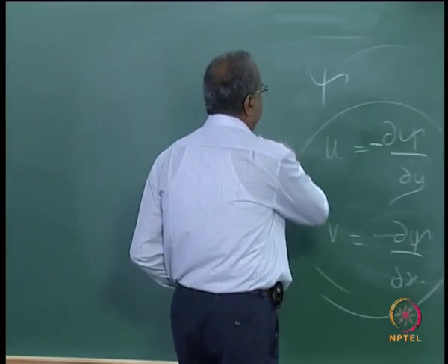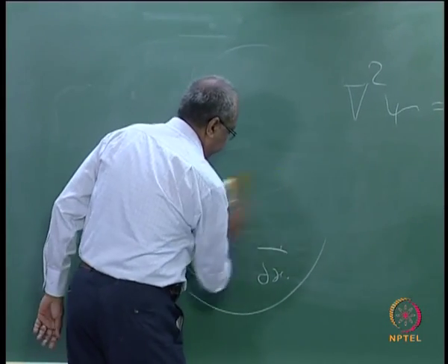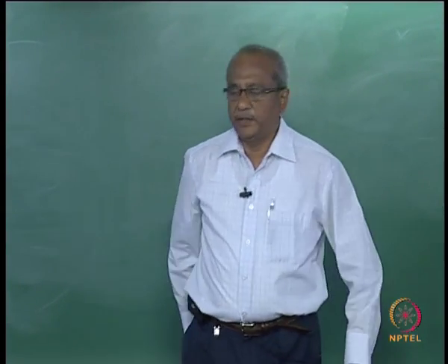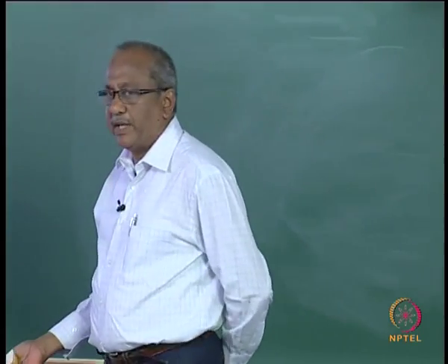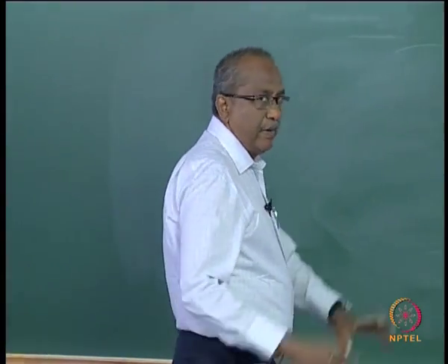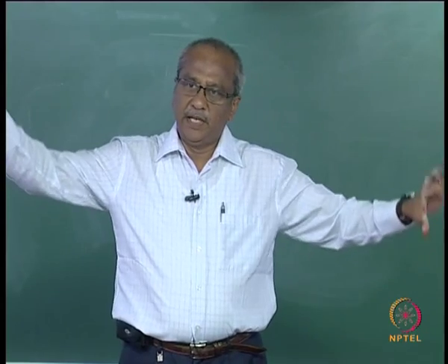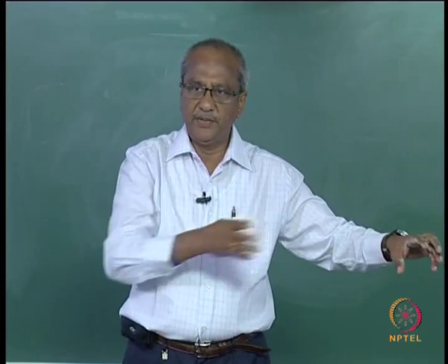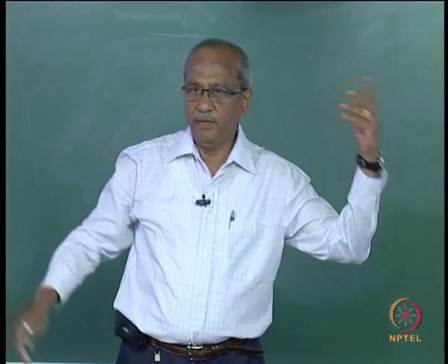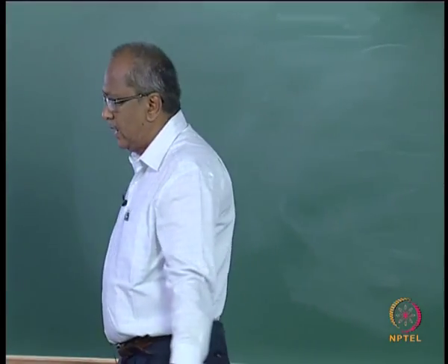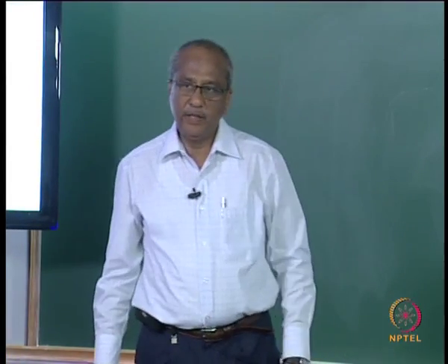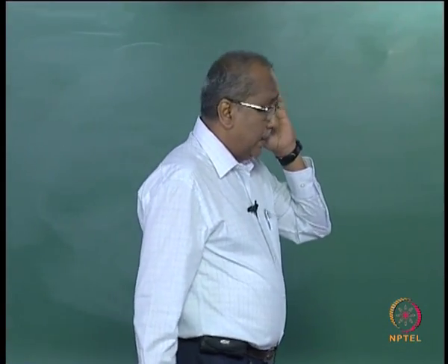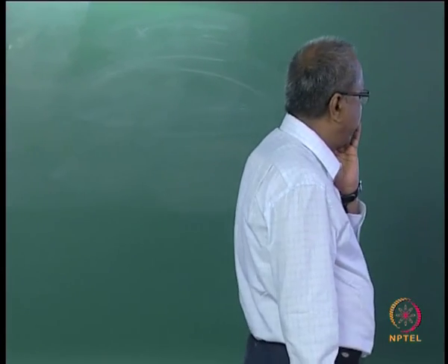So now we will look at the Bernoulli equation. Why Bernoulli equation? The common example for the application of Bernoulli equation is when you have a pipeline, either tilted or horizontal, and there is a flow taking place. Pressure at one point is known, you want to know the pressure at the other end, or maybe you are interested in finding out the pressure drop, etc. So it has a wide application, particularly in the field of fluid mechanics.